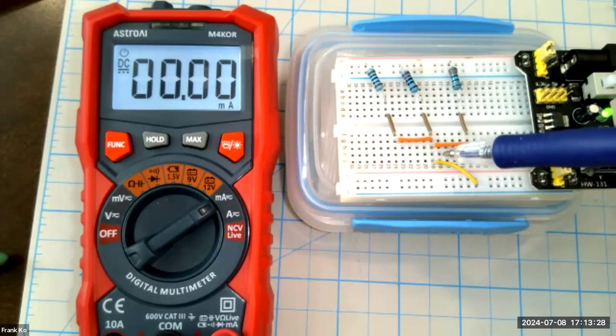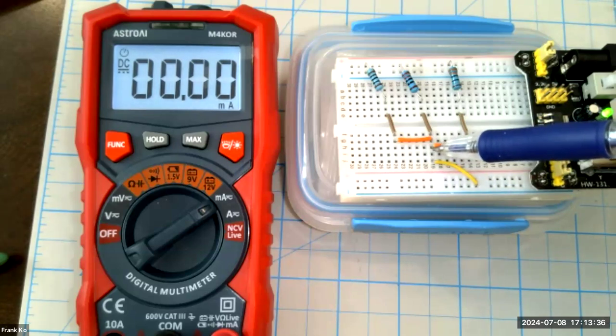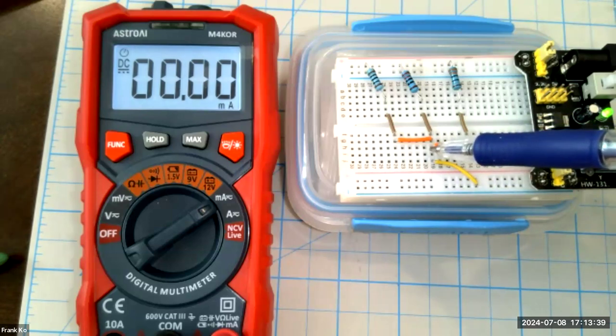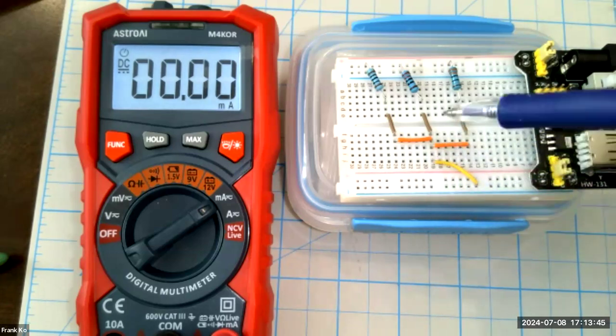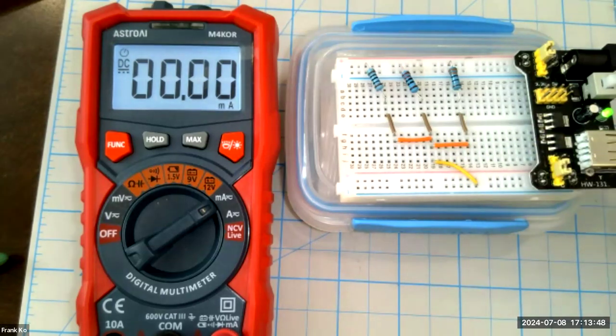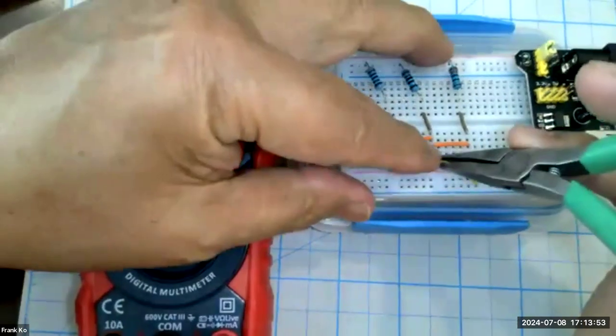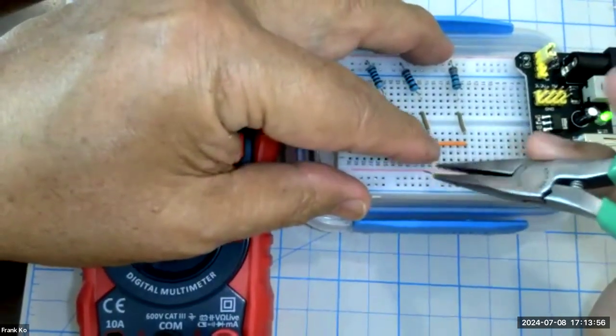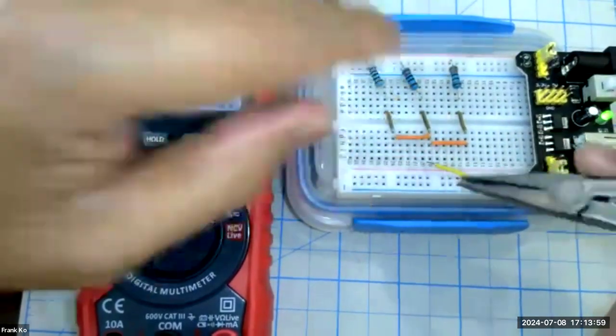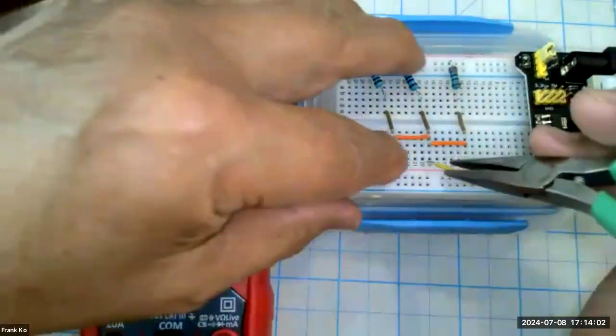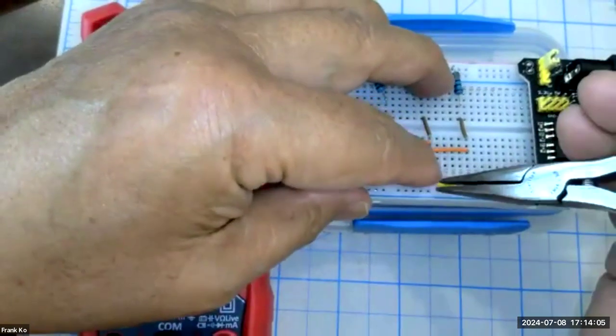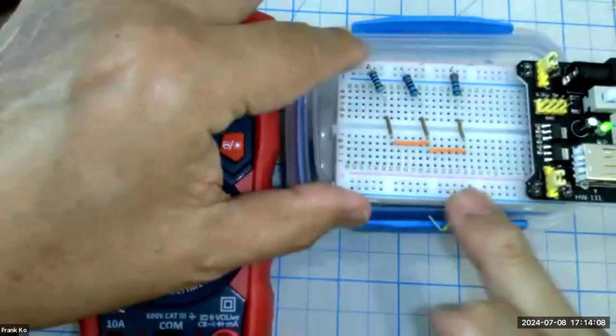So what I'm going to do, in order for me to measure total current, is create an open right here between where the yellow wire connects to where it connects to the two orange wires connected together on row 19. That will create an open, and from this open, I should be able to measure my original 87.87 milliamps. So I'm going to show you how we're going to do that. I'm going to very carefully just raise this up and stick this off the board somewhere, doesn't matter where, just leave it open like that. I can actually take it off the board like so. All right, so now I have an open.